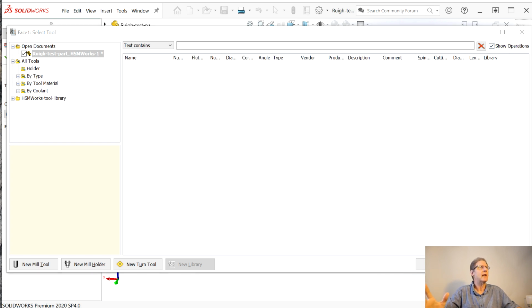So I'm trying, this is a help file. You go to Windows and find in Program Files, HSMWorks, libraries, and you copy that somewhere. Then you've got to know to highlight all that stuff, right click it, and where it says read only, unclick the read only attribute on all those files inside. There may be a way to do that in here. I am not sure, because you go on the internet, and that doesn't help you.